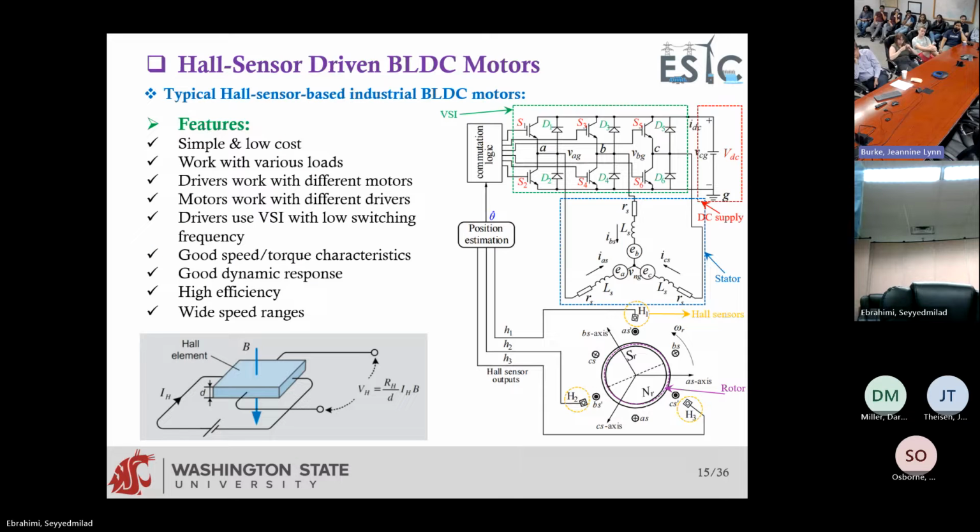So what we have here is a DC power supply, which can be from another stage of AC power supply, it doesn't matter. You have a DC power supply that is driving 6 switches. So it is connected to 6 switches, and these switches are driven by a logic. And the 3 output terminals of the inverter are connected to the stator winding of the machine.